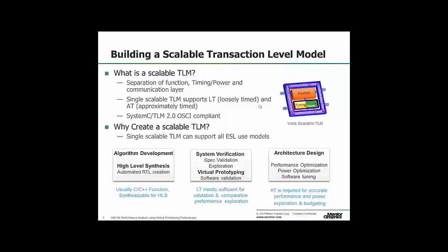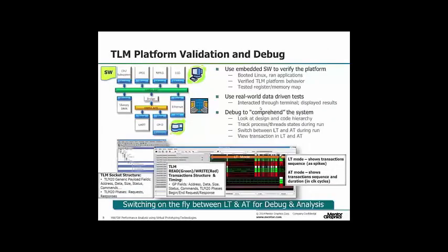Typically the best approach to validate a platform is to run some real-life software upon it and use that as the stimulus for the platform. So for example, if we can boot Linux and load real-life device drivers and applications that access the registers in the custom peripherals that we've modeled, then we can be more confident that the platform is working correctly. At least we've got the boot up stage working.